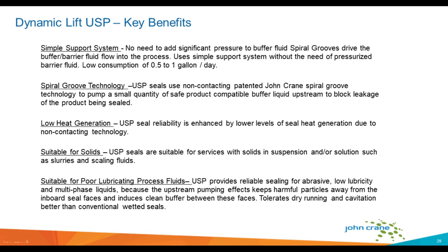There are some advantages to approaching an application with this type of face treatment. Really, we're getting the advantage of a dual pressurized seal and bringing that to an unpressurized support system. The actual pressurization of that low pressure fluid is achieved by the seal faces themselves, utilizing the geometry of the spiral grooves.